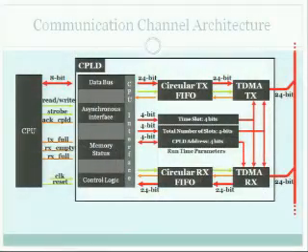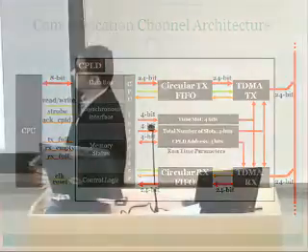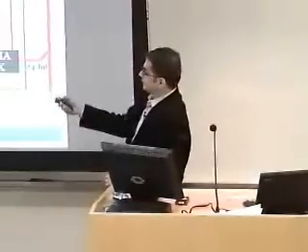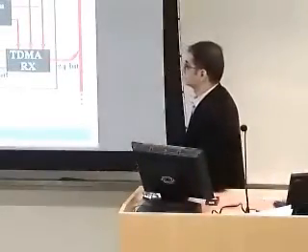Now, here you can see the overall architecture as it has been designed and implemented on an actual CPLD. Initially, we have a CPU interface for doing the communication. The CPU can pass data to be transmitted or can set runtime parameters of the CPLD, such as the time slot, the number of slots, and so on.